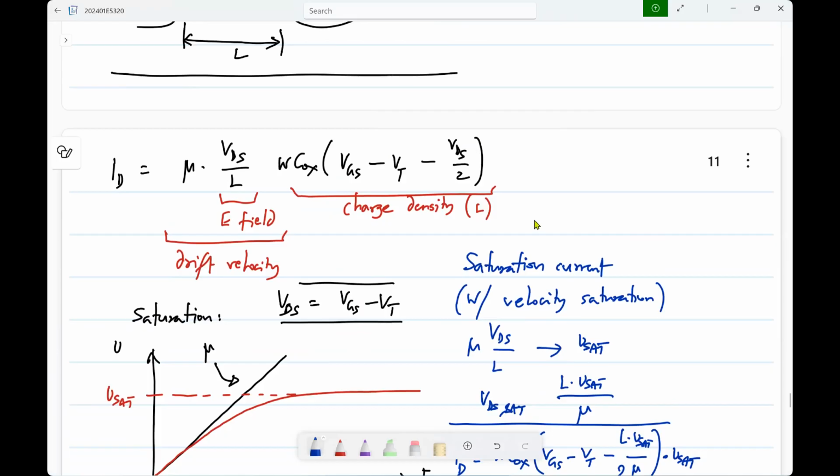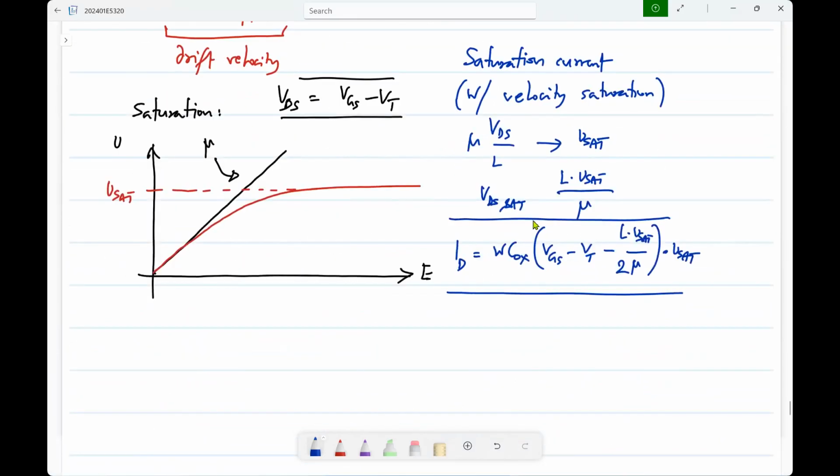So this is the expression for the saturation current. Okay. So now what differences do you see between this and originally, of course, what did we have? We had ID to be mu Cox W by L times VGS minus VT square by 2. Okay. What are all the differences? First of all, it's not square law anymore.